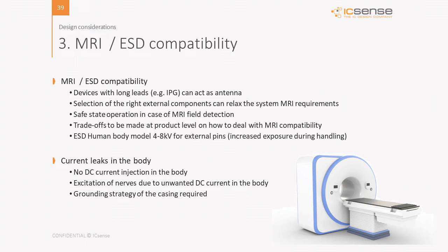Also, you can define certain safe states, so that in case an MRI field is detected, the chip will go into a safe state. As I said, you need to make the right trade-offs at product level on how to deal with MRI compatibility. Also, ESD is an important one, especially for the pins that see the outside world. For example, those pins can be exposed to 4 up to 8 kV. When the surgeon is using plastic gloves, this will increase exposure during handling.